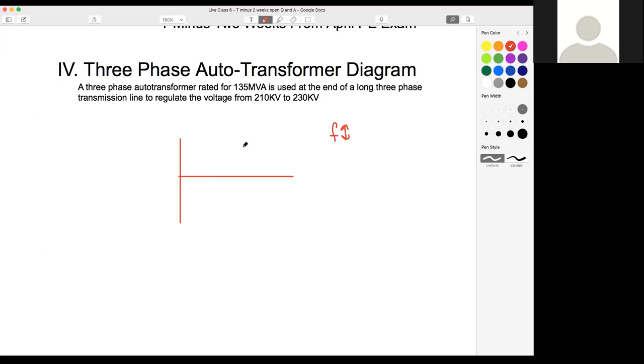But since the VFD is not a true AC source, it sends pulses. It sends big on or off pulses, individual square waves really quickly. And it can either send bigger ones or smaller ones with a varying wavelength. Essentially, to the machine, it's almost no different than seeing an AC sine.